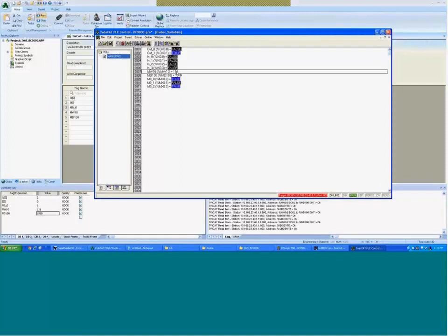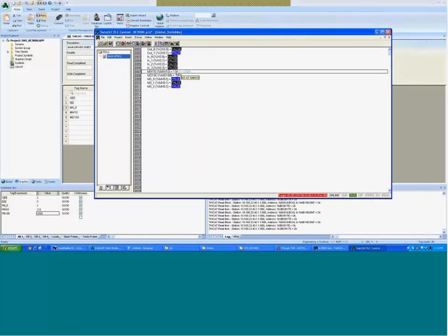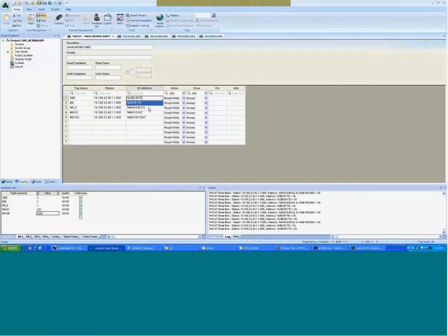I'm going to change the value on the PLC. So for the MW10, I'm going to put 222. I'm going to write to it. You can see already the value on Web Studio. Okay, I'm going to put here, let's say, 2222. I'm going to write to it, and you have that on Web Studio as well. So the difference is that I can have the tag name on the I/O address configuration. All the rest is pretty much the same.